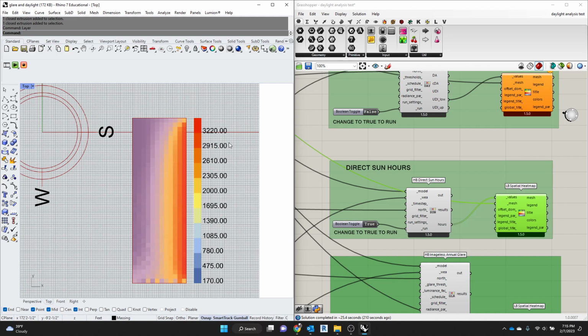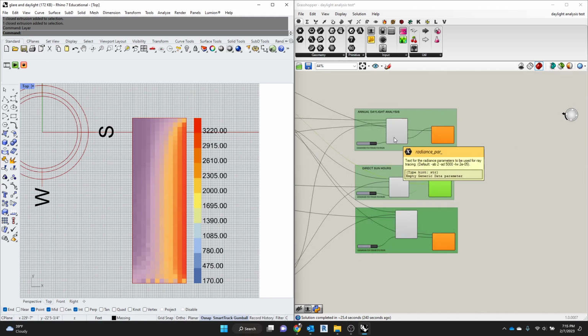All right, so your windows are there, there, there. South, this side. Which one did you run? Oh, that's a different analysis. So see if this one pops up. I double clicked it. If that doesn't work, then we'll take a look again. So just so everyone knows, I was running this middle analysis, which is direct sun hours. These other ones will show differently, so we'll talk about them in a second.